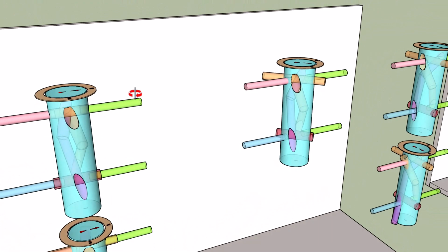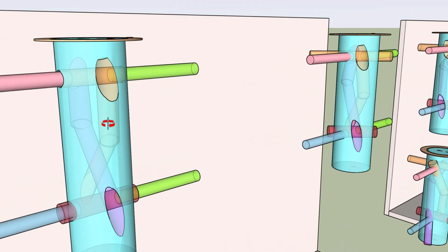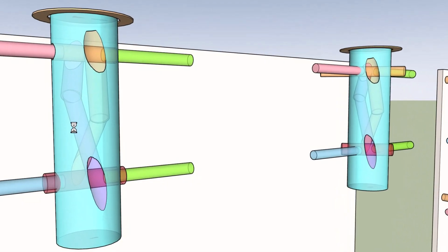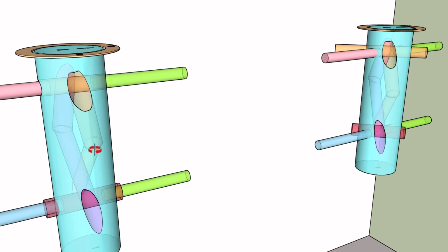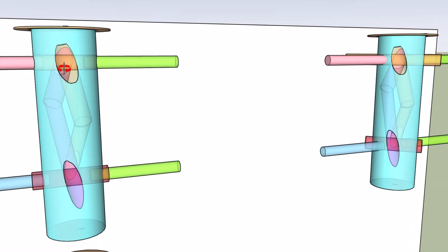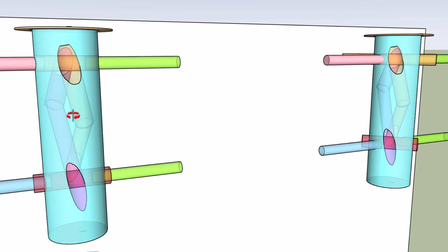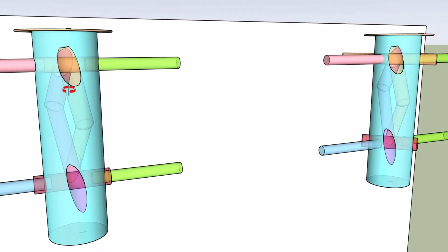And if you look inside the valve, I altered the opacity so you can see inside of it. It has these channels in here, kind of a little bow-legged. And the reason for that is to keep the separation between these, so that the high pressure here, we don't want it to rupture the metal.